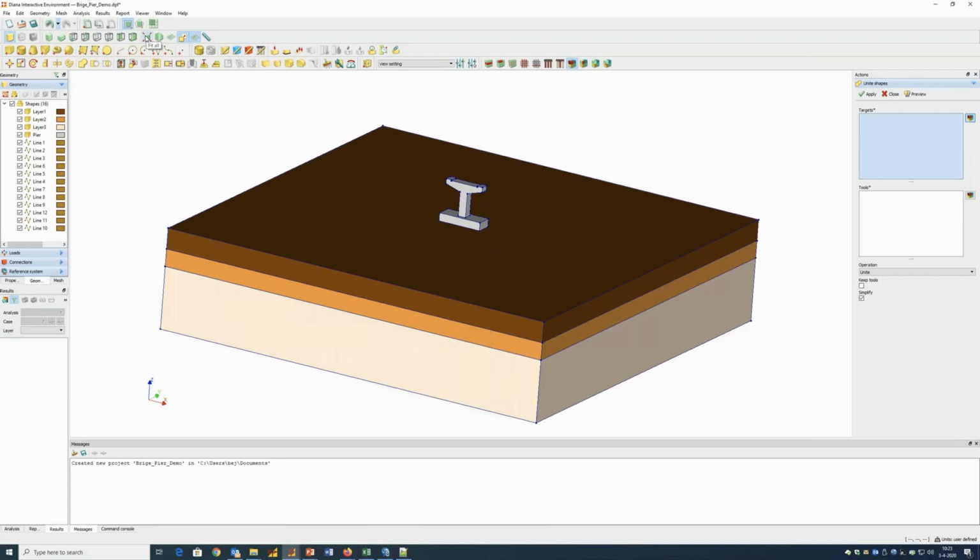As you probably remember, when I was presenting the model, I said that we are going to use 2 sets of piles. One set for the piles into the concrete foundation, and one set of embedded piles for the part inside the soil layer. So it means that we have to split these piles.